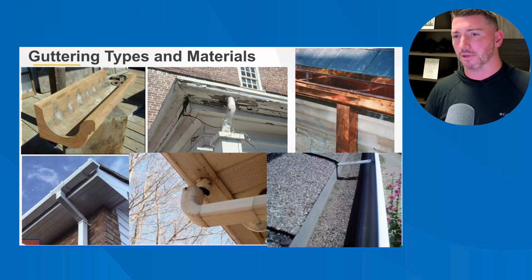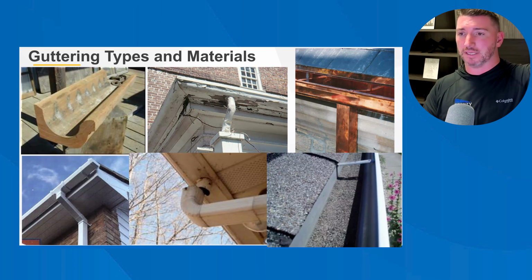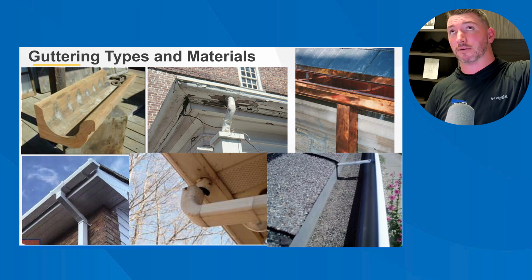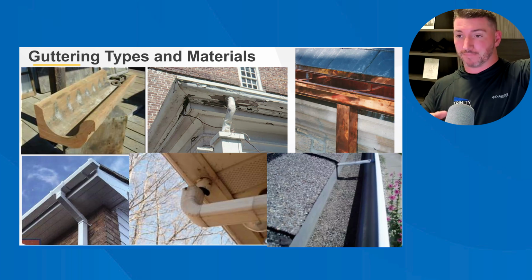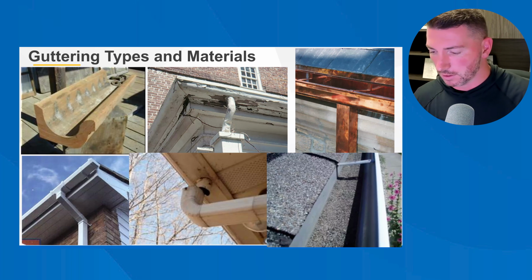If you walk up to a modern building, you see that it has seamless aluminum gutters. Great news, there probably will not be a tremendous amount of leaks in the field area of those gutters. So your focus should be on the corners. See if the corners were sealed up correctly. See if the downspouts were lapped correctly, right? All of the bottom pieces should be tucked into the top pieces, did I say that correctly? Sorry. The top pieces should be tucked into the bottom pieces. So as it comes down, the water shouldn't be able to find a seam, if that makes sense to you.